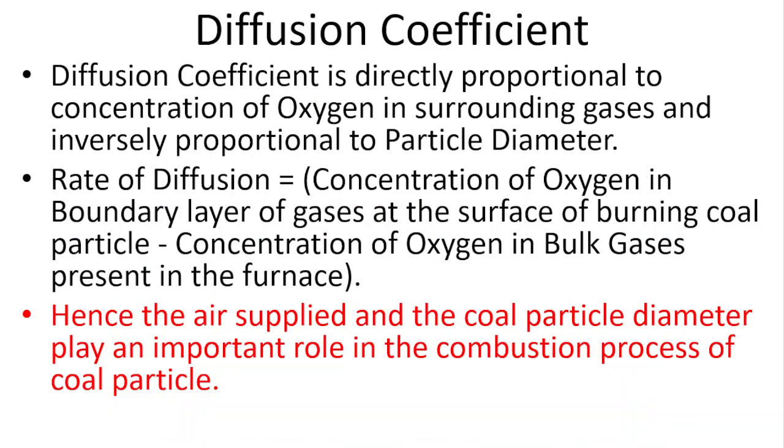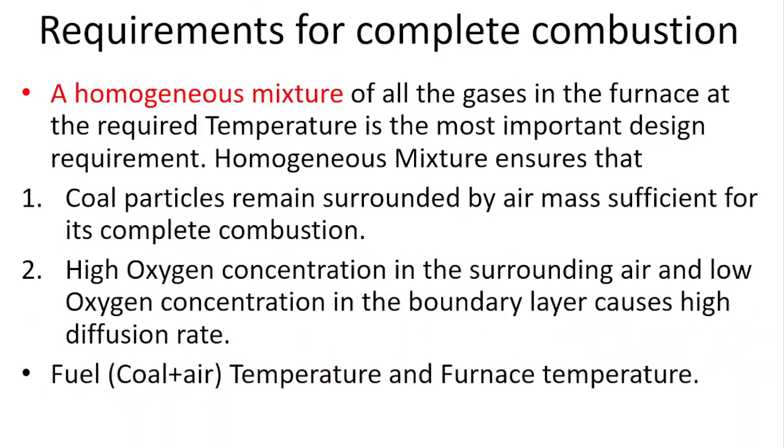soot particle. The diffusion coefficient is directly proportional to the concentration of oxygen in the surrounding areas and inversely proportional to the particle diameter. So the rate of diffusion is equal to the concentration of oxygen in the boundary layer of gases at the surface of the burning coal particle minus the concentration of oxygen in the bulk gases present in the furnace. Hence the air supplied and the coal particle diameter play an important role in the combustion process of a coal particle. So, the requirements of complete combustion.